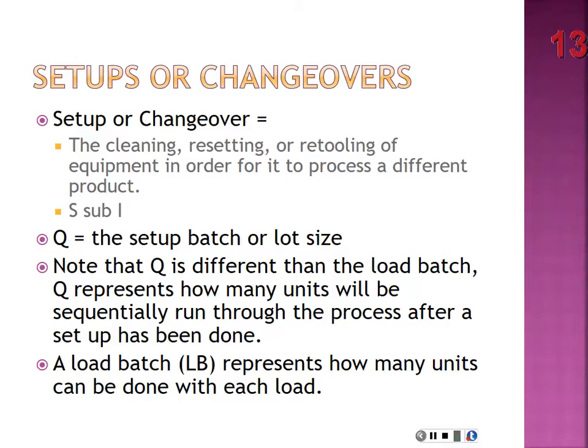All right. So that's the load batch part of it, but now we also have to consider setups and changeovers, because they impact how much we can actually get done. So consider now the effect of setups. In a process that involves multiple products, it may be necessary to set up the process each time the product is changed. The cleaning, resetting, or retooling of equipment in order for it to process a different product is called the setup or changeover time. For instance, the painting robots in a paint shop require draining the pipelines and cleaning up the painting heads each time the color is changed.